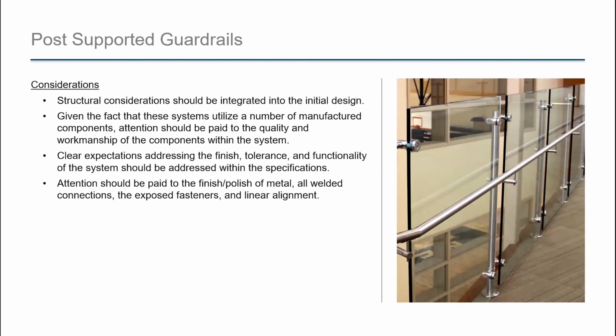Considerations when choosing this type of system to keep in mind are early in the design process. Typically, we see these designs come up as an afterthought, and we are left with little to no structure to attach our railing. Remember earlier in our presentation the importance of structure we discussed as part of the 3 S's in relation to a system's performance and method by which the railing is attached to the structure? This is a perfect example of why upfront coordination with the specified railing manufacturer is important to an efficient design process.